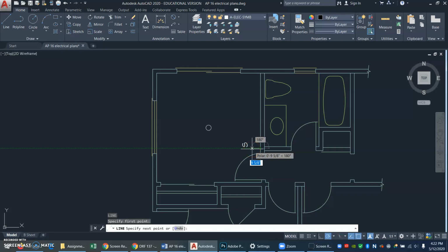I'll just make a line. I don't know how long to make it. I don't care. I'll just make a line. All right. And now I'll move my letter S a little bit. M, enter for move. I'll click on the S. Now, if I use O-snaps, it's going to be funky because the O-snap point for the letter S is out on some corner. So I'm just going to eyeball it. I'll just click out here in space for my base point, and then click down here somewhere.